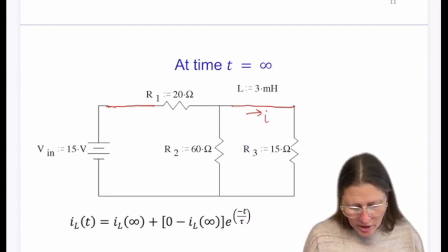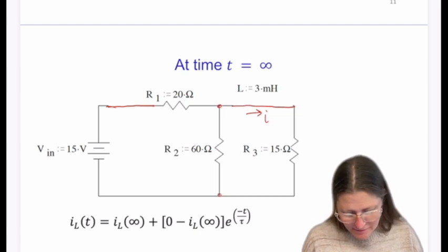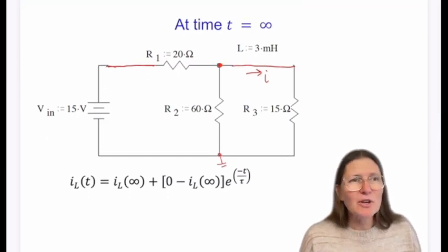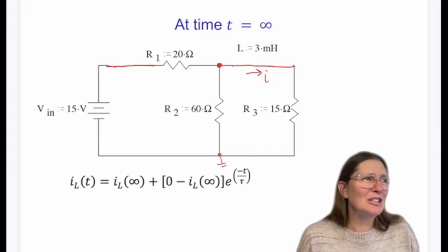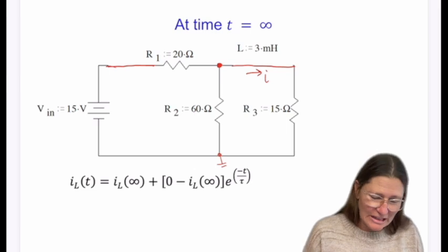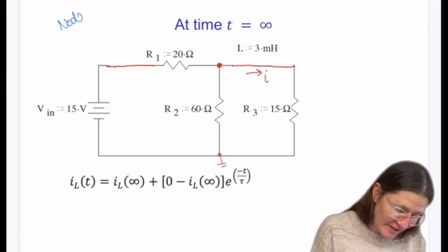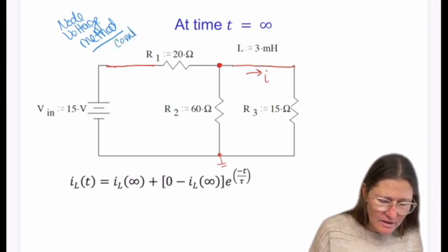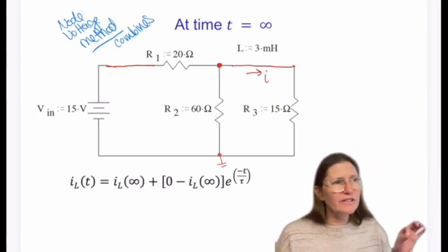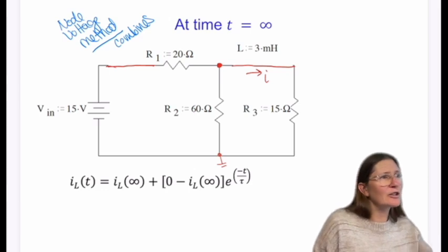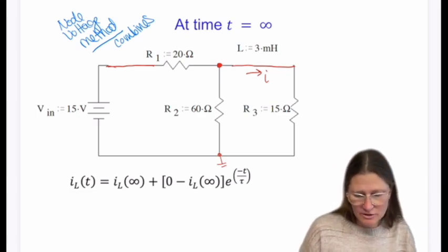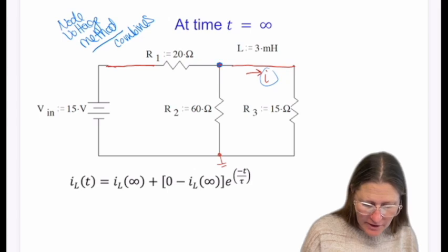And so with this one, you have several options to solve for it. Can I give you guys a little technique I like to use here? So this is called the node voltage method. What it does is it combines your current summation and your voltage loop all in one step, so you can look by inspection and write your equation.